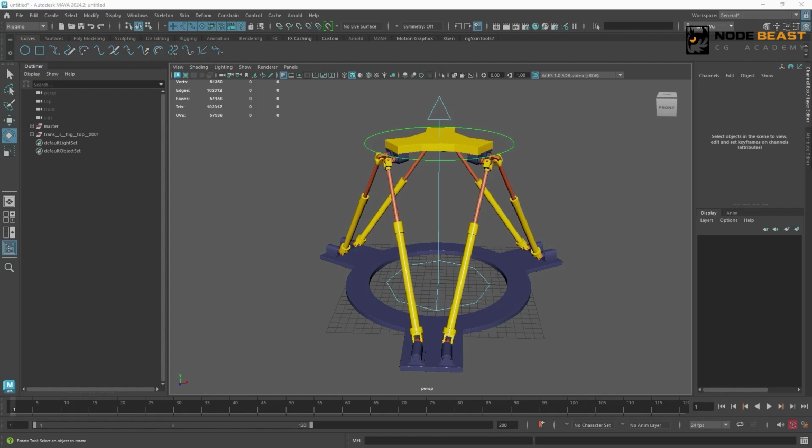When we go to rig these parts, we generally start with the main behavior, and then gradually move to the finer details, and rig those details. For this piston structure, what is its main behavior? Let's take a look. It's clearly divided into an upper and lower part. This upper part will always point at this bottom point. And this lower part will always point at this top point.